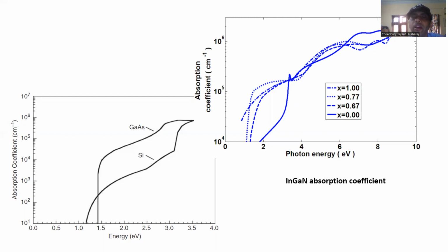They are something like, in the order, for electrons, the effective mass is something like 0.2 to 0.3 times the free electron mass, while for holes, it is something like 1 to 1.5 for two of the kinds of holes, and then slightly different for another kind of hole. So the transmission coefficient for holes tends to be low. So we may need to do some different kind of optimization, like adding some polarization-carrying thin cap layers to induce severe band bending in order to get good transmission coefficients.